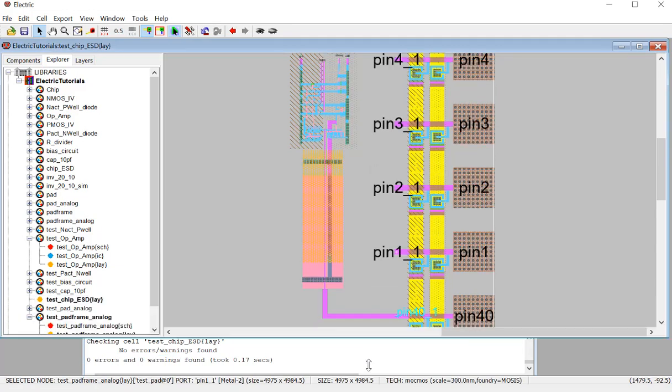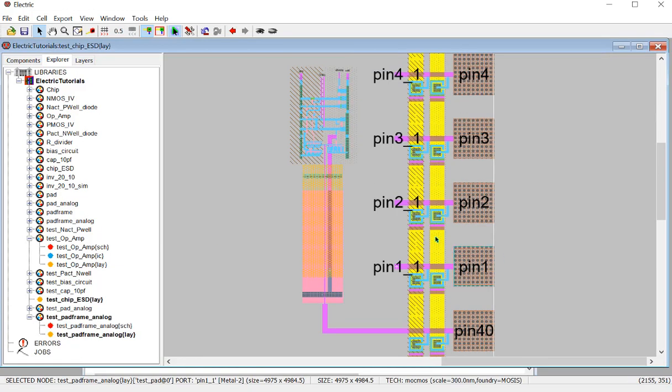And then we want to connect from top to bottom, okay? So top to bottom, let's start from here to top. So the first one is B. You have to press Control, right? If you don't press Control, you hover your mouse to the top, there's nothing shows up. You have to press Control. See the port, it just shows up. You pick that up. So that's VDD.